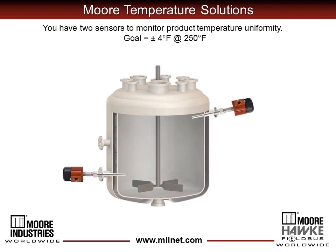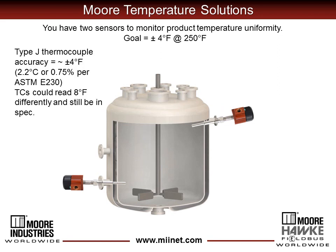In this example, we're concerned about maintaining temperature uniformity of the product in this vessel. The process folk have given us a goal of a product uniformity of plus and minus 4 degrees Fahrenheit at the operating temperature of 250 Fahrenheit. We're going to use 2 sensors so that we can better indicate product uniformity.